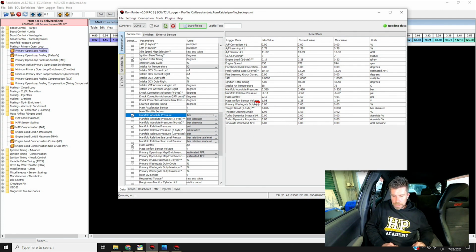We also want to look at our primary wastegate duty cycle. So if the parameters we've just logged, basically our target boost versus our measured boost, that's going to show us how close we are, how much error we've got, are we overshooting, are we undershooting, and we also can use that during a ramp run to basically sort of trim the boost target map so it is realistic.